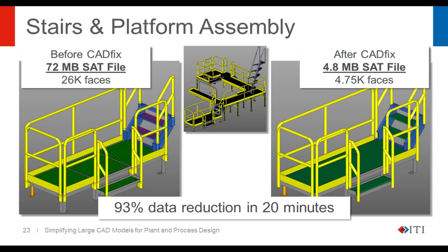I've zoomed in on a local area to see it. But before, the model was a 72 megabyte SAT file with 26,000 faces. After CADfix has processed the file, we've ended up with a 4.8 megabyte file with 4,700 faces. We got again, about a 93% data reduction with 20 minutes of processing time.